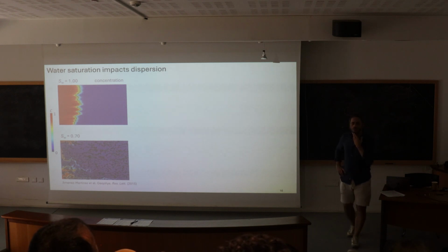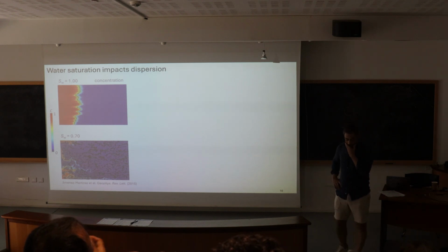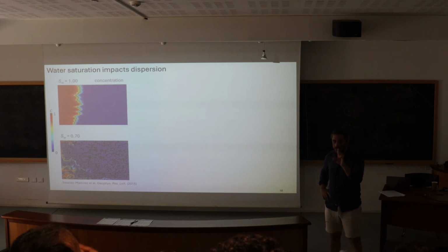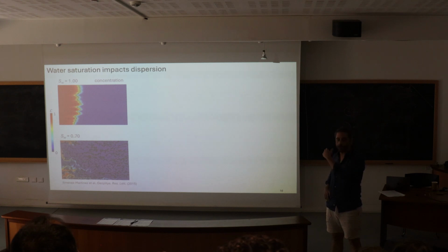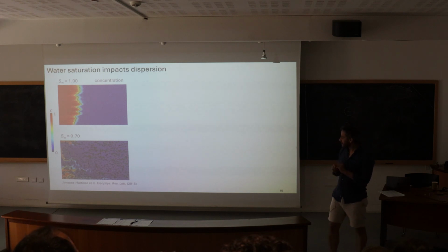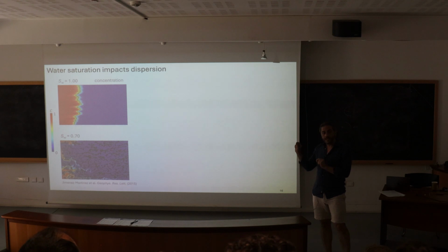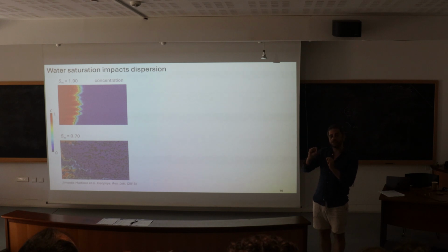it will move. The air, right? Because you are dissolving it. No, we are not dissolving anything. Here let's assume that the immiscible phase, in this case air or whatever other immiscible phase, it can be a hydrocarbon, is not dissolved in the liquid phase. And in this case, the flow rate is so small that viscous forces are smaller than capillary forces, and with this flow rate, you cannot move the immiscible phase.